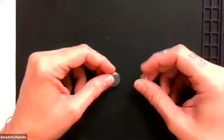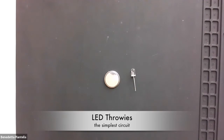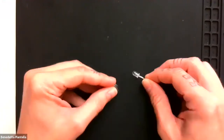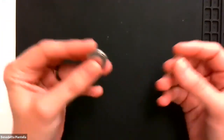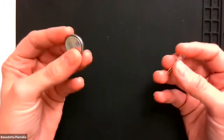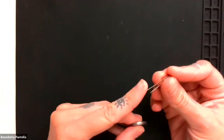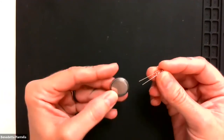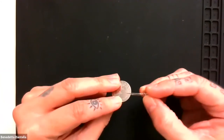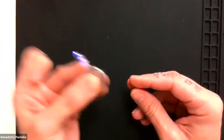And if you don't want to do an entire paper circuit using copper tape, there's also a super simple way to add, for example, a light to your electronic project. This is called an LED throwie, which, as the word says, is an LED that you can throw. And again, talking about the polarization of this component, if you directly place the positive end of your LED to the positive side of your battery and the negative to the negative, and you sandwich it together, you have a little light.